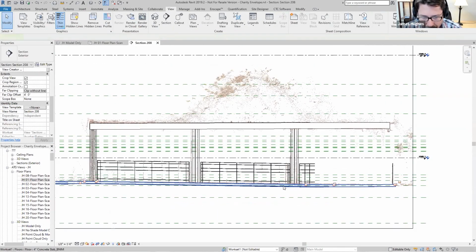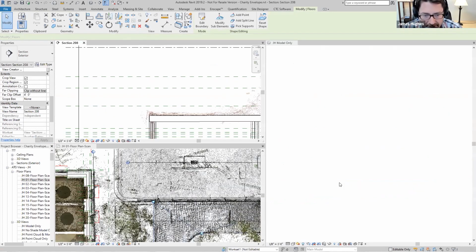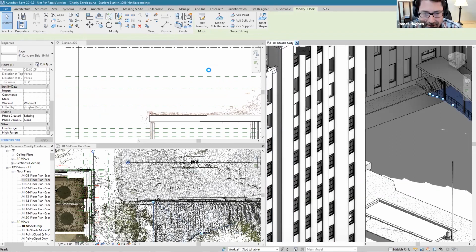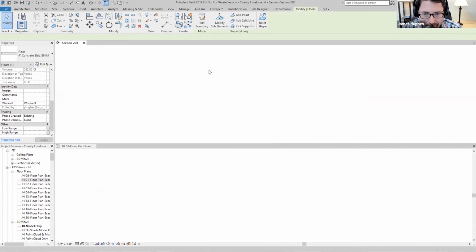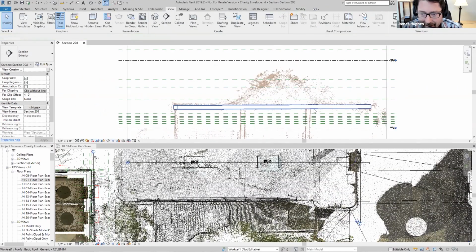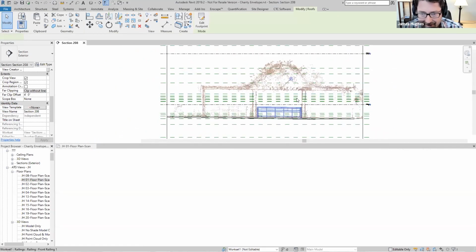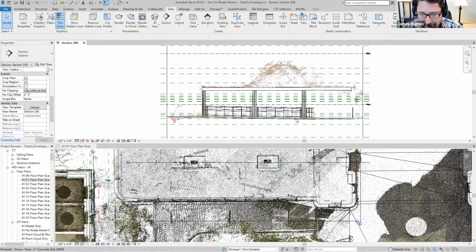Yeah. And so here I've got a floor, and I can coordinate this if I window tile it. Ooh, or I can just confuse myself. Let me close that real quick. I like to coordinate this plan view and section view so that I can see how to properly elevate each point. Normally it's faster than that. There we go. So you select your floor. Watch that be the awning. Yeah, that's the awning. Sorry. Select your floor down here.